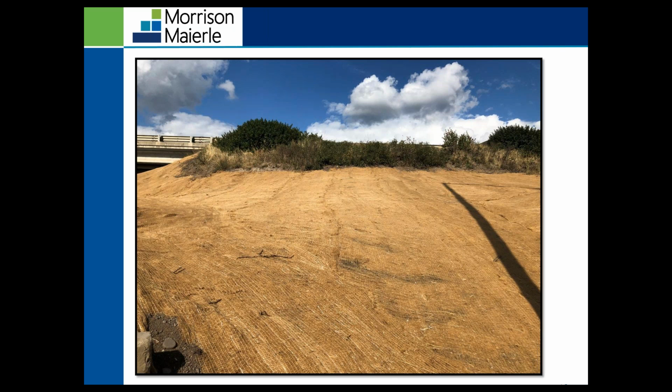Whatever you use for erosion control for disturbed slopes, whether it's hydraulic or straw mulch or these erosion control blankets, you want to make sure that you're roughening this disturbed soil, placing seeding after you roughen it, and then prior to the installation of the erosion control. So this is on any disturbed soils where you're trying to get some vegetative growth, that final stabilization. This is a good BMP to use. You can start to get some vegetation to grow, which then creates some roots to be established, which then binds that disturbed soil. With these BMPs, though, they're usually labor intensive, which could affect your decision to choose this.